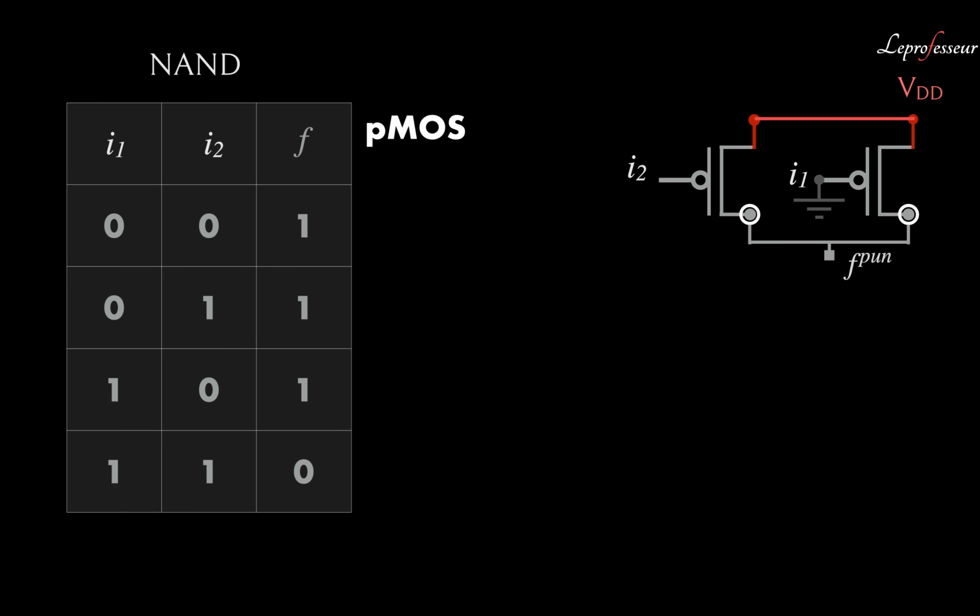So what if we connect I1 to ground? What's going to happen is that the holes will flow through the channel and will reach the other terminal. So the output at the other terminal of the I1 PMOS will reach logic level 1, or a stronger 1.